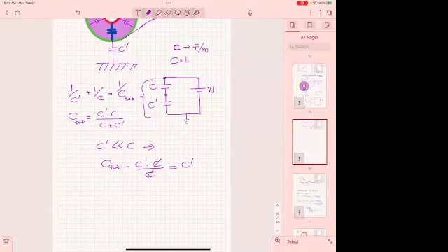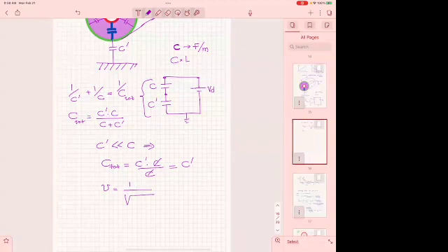And that is called the group velocity. So when you send bits per second, that tells you how fast the bits will go. And in fact, in ideal lines, the group and phase velocity are about the same. So say the velocity of the line is going to be what? 1 over square root of LC.